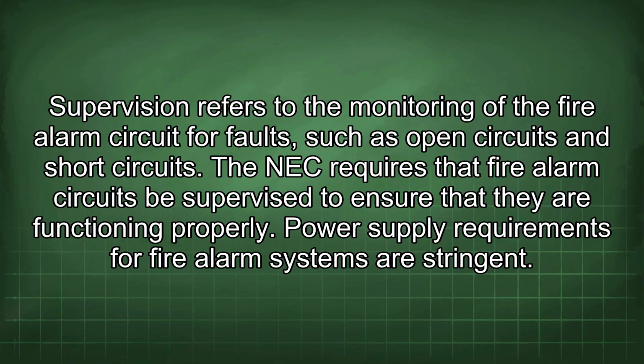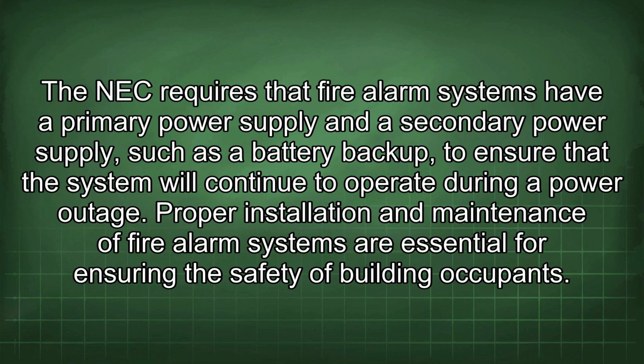Power supply requirements for fire alarm systems are stringent. The NEC requires that fire alarm systems have a primary power supply and a secondary power supply, such as a battery backup, to ensure that the system will continue to operate during a power outage. Proper installation and maintenance of fire alarm systems are essential for ensuring the safety of building occupants.